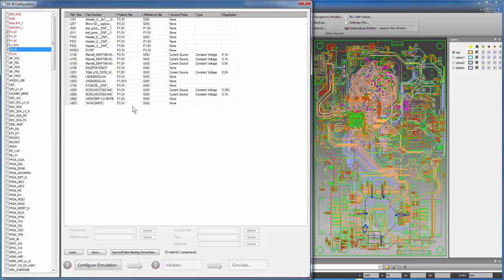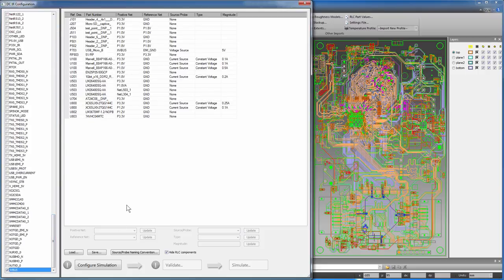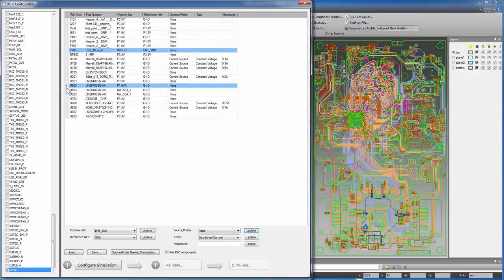Next, define voltage sources. First, include the nets L3041, L5031, and XV-bus. These nets are on the output pins of the voltage regulators. Multi-select P703, U503, and U802. These denote the micro USB connector, multifunctional power management unit, and buck step-down regulator, respectively. Now simultaneously define voltage sources.